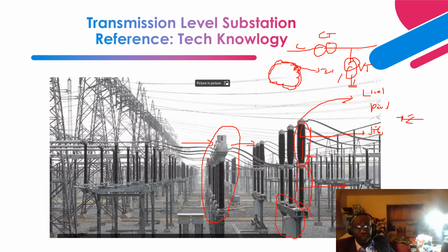During the close operation, an arc can form. Or if the circuit breaker needs to open, due to an opening action or a fault interruption, the movement of this movable contact can create an arc.